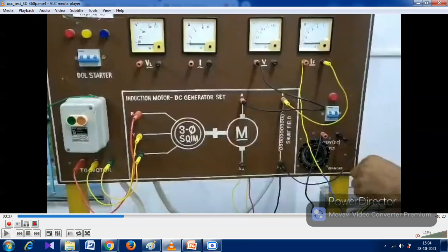Yes sir. So if we provide a voltmeter on those two terminals, can we say that these two terminals are open? Yes sir. That's why when we perform the OCC curve, or open circuit characteristics curve, we are just adding a voltmeter on that terminal.